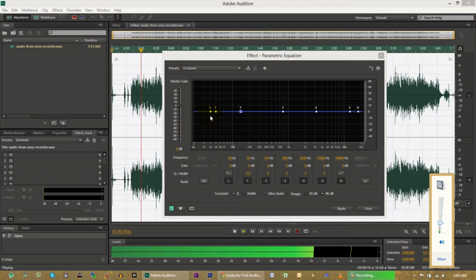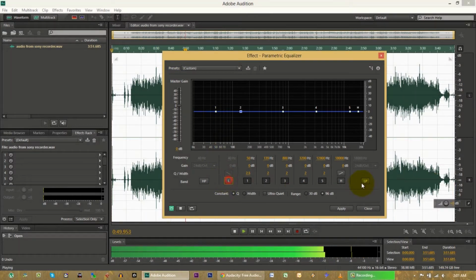First thing that I want to do is get rid of the lower frequencies, because remember how I said that anything below 20 hertz none of us can probably hear, or very few of us can hear, but even the stuff just above 20 hertz sloping up towards 50 or 60 or 80, even that stuff can be reduced a little because most people don't hear it. It's low energy, it's kind of a rumble, it's not really good sounding audio. So the way I can do that is I'm going to put a high pass on here, and basically high pass means only the higher frequencies get passed.